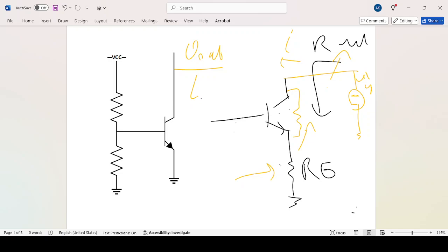So this increase in the voltage, in small signal, generates a current by the transistor that is not working in favor of I. So you would have something like minus gm vbe created by this effect, and as you can see, the current of the voltage source will be reduced by this phenomenon.